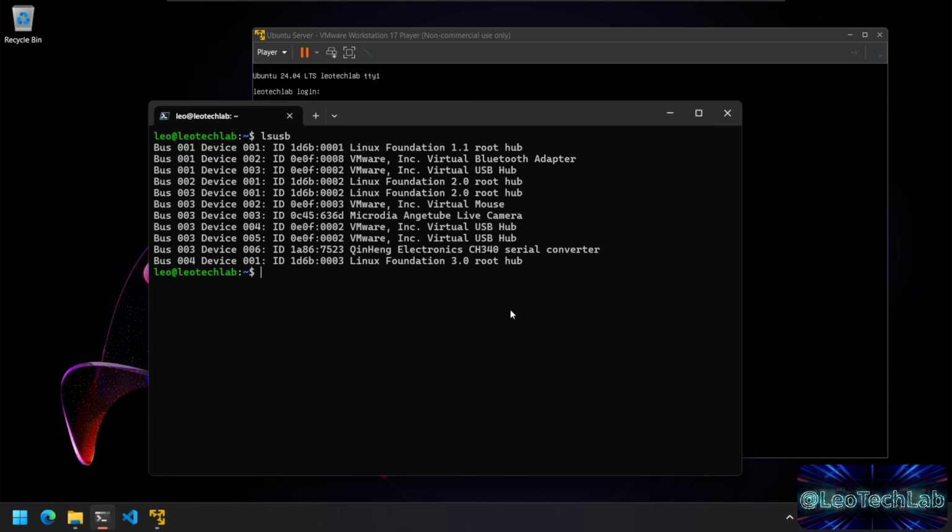Quick warning regarding the USB connection of the 3D printer. I strongly recommend that you prevent power from passing through the USB cable, so that it does not interfere with the printer's electronics. I talk about this in more detail in the requirements section of my Octoprint installation videos. The links are in the video description.